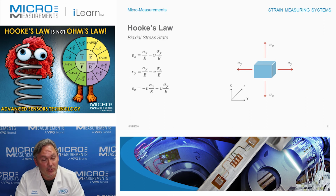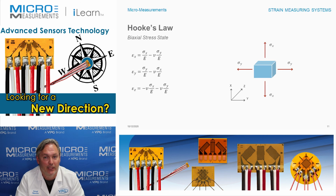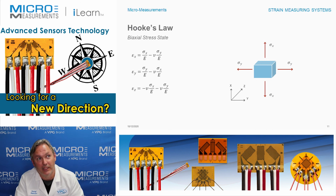If you're not sure about direction, that's where you typically use a 3-element rosette that's got 3 separate grids on it, and that allows you to solve for principal strains and direction or principal stresses. So keep that in mind. If you're going to use 2 gauges to solve for Hooke's law with a biaxial stress state, you need to know direction. If you're not sure of direction, you really should consider using a 3-element rosette, and we've got a wide variety in different sizes and different constructions that you can choose from. But from the 3-element rosette, you can calculate principal strains and direction, as well as calculate principal stresses and direction as well. I hope that helps you out.